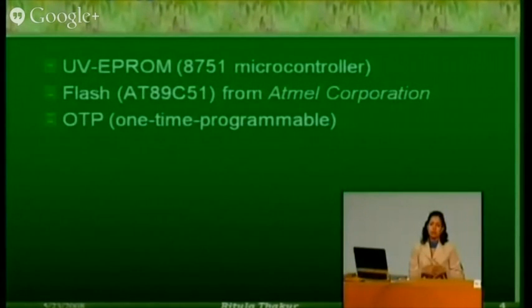So the other type of memory is in-system programmable flash memory. In-system programmable में क्या होता है कि आप अपना जो, नाम से पता चल रहा है, in-system means आपका जो controller है, it will remain in the system itself. You will directly connect with your PC or your laptop. Within a few seconds it will erase the older one and it will rewrite your program. So within a few seconds you are able to erase and rewrite your old program. One such type of microcontroller is the 89C51. जो 89 वाली series रहेगी, that means उसकी type of memory जो है, that is flash memory.